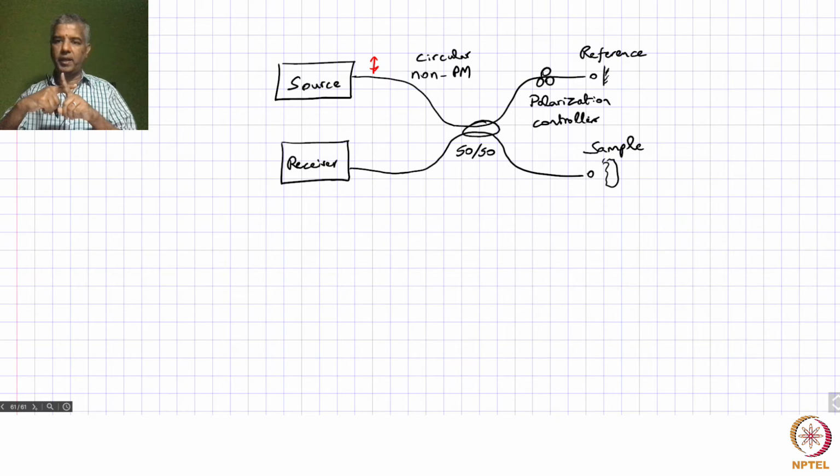So, that provides some birefringence, what is called stress induced birefringence, on the fiber, and you can make it such that you wind with a certain number of turns, and that actually behaves like a quarter wave plate, meaning it gives you basically a pi/2 phase shift, pi/2 retardation of one polarization with respect to the orthogonal polarization,